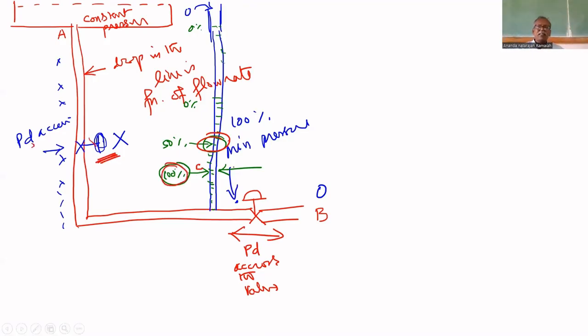I can do the experiment. That experiment is called inherent characteristics. What you have to do is, for 100% flow rate, note the column level in the single column manometer. A single column manometer means a transparent tube connected just before the valve. The level in that column will be minimum for 100% and maximum for 0%. So by using this hand valve, you can always adjust the level equal to 100%, so that you keep the pressure drop across the valve constant.